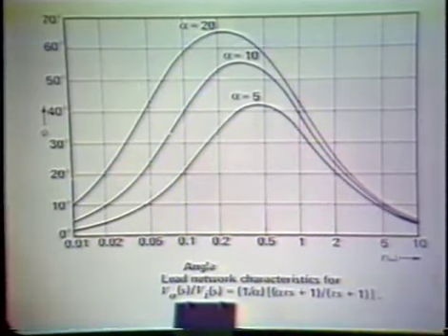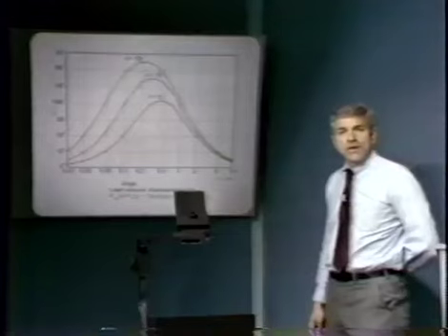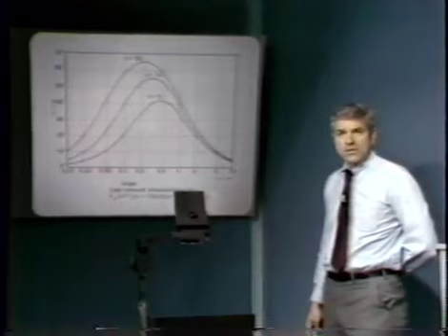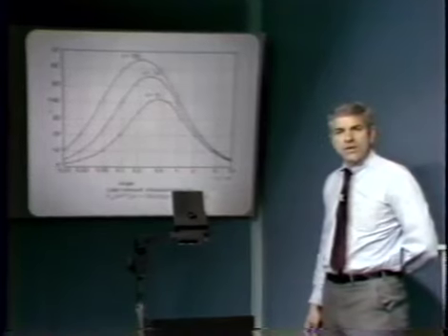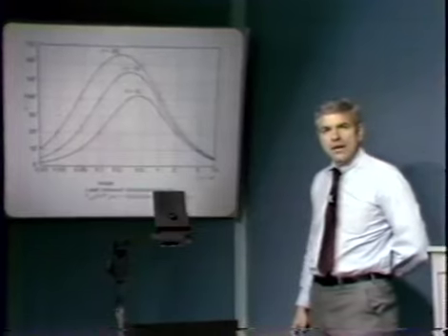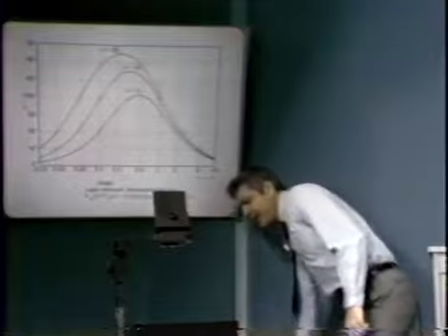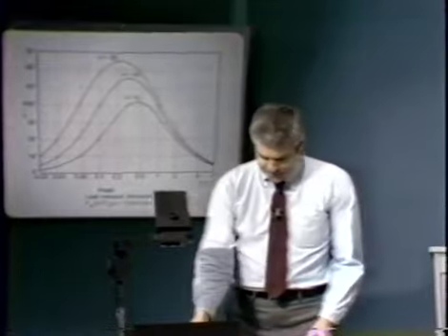Remember that we're interested oftentimes in getting phase margins in systems on the order of 45 degrees, and so 45 degrees of positive phase shift can make a very important improvement in the performance of a system. Here we have transfer characteristics that give us that sort of phase shift at the location of the 0. Well, let's look back at the magnitude characteristics for a moment.